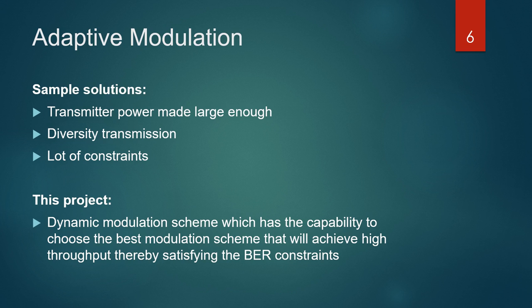However, since the transmitter modulates the signal based on the worst case scenario for that particular channel characteristic that it has received, the method will lead to low utilization of the channel. Thus, adaptive methods have to be employed in order to maximize spectral efficiency and the throughput, to have high channel utilization and achieve high data rates.